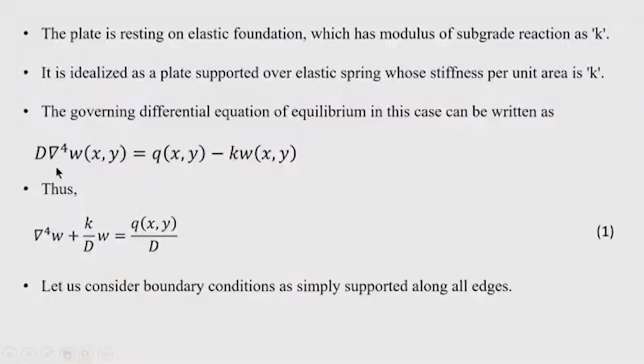Okay. So, this biharmonic operator I have explained to you earlier, and after expanding we can write this differential equation with all the terms. Okay. So, thus ∇⁴W + (k/D) W = q(x,y)/D.